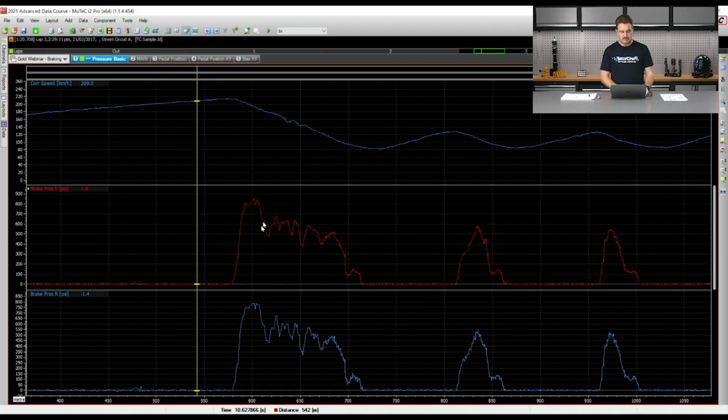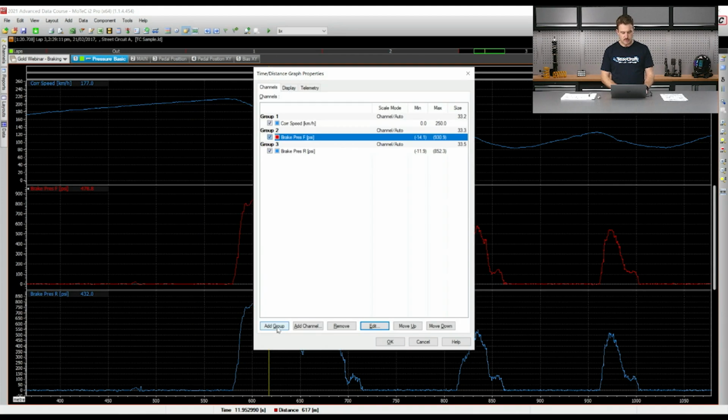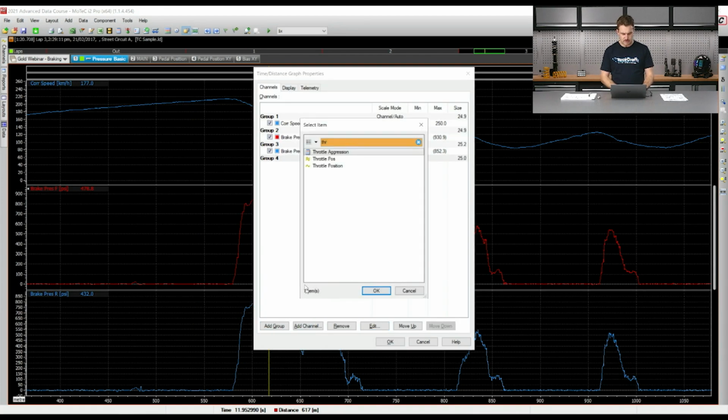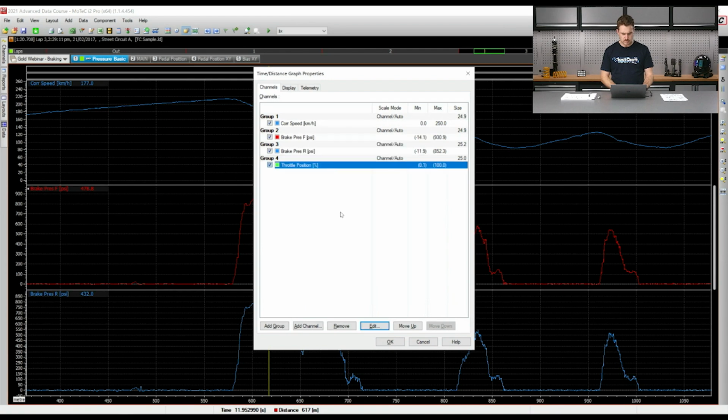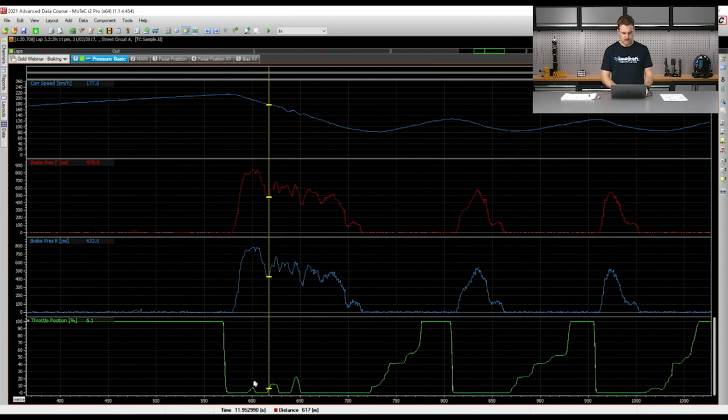Now there are these features throughout here, these little dips in here, and what I think they will be are throttle blips. So let's have a look. Let's add in some throttle trace in here as well. Yeah, so what we've got going on down there is see these little blips in the throttle as they go. This is going down 3 gears in this case.